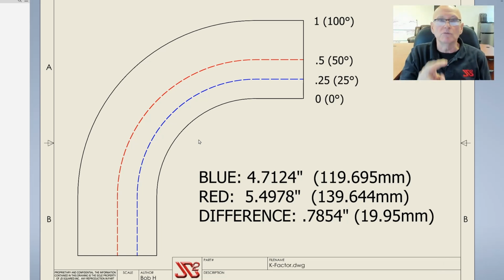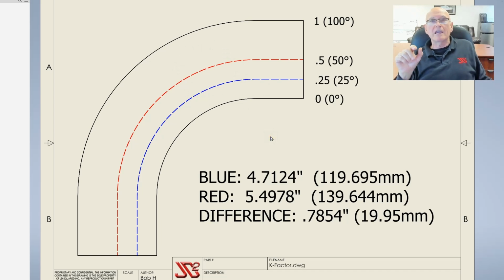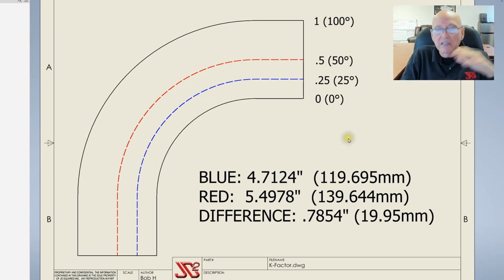Okay, so you're going to need those two numbers in order to create a part of the right size. So let's look at this drawing I've got in front of me here to explain why, if you have the K-factor wrong or the bend radius wrong, bad things happen. Now, first thing you need to do is tamp down your expectations a little bit. It's not a perfect world. So when you get a K-factor and a centerline radius and you go out on your bender and you bend everything and man, oh man, it worked absolutely perfect. Then a month later, some more steel comes in and this time you go out and bend it and the doggone part's off by 1/16 of an inch.